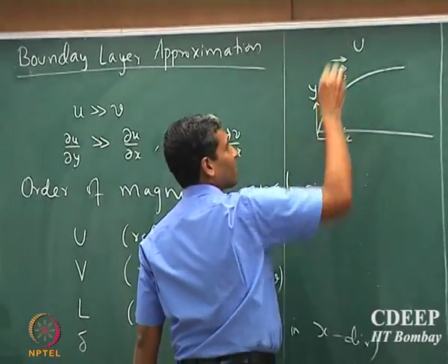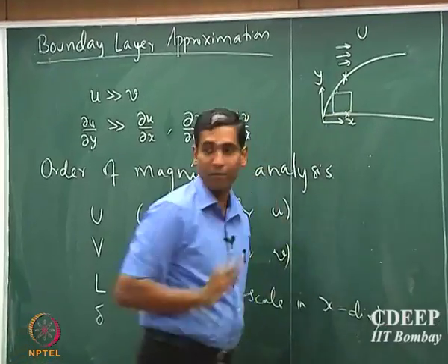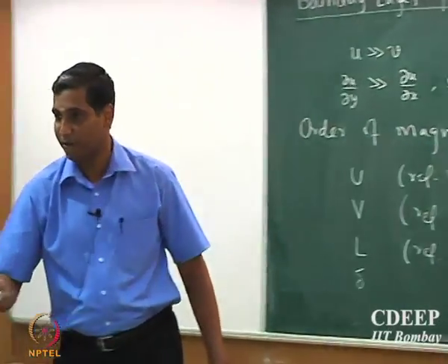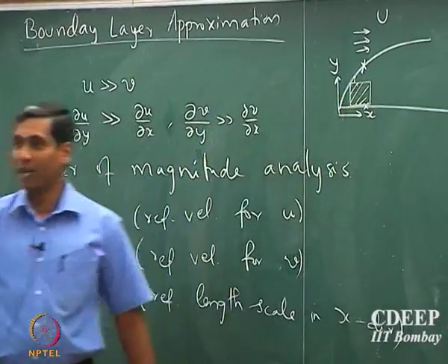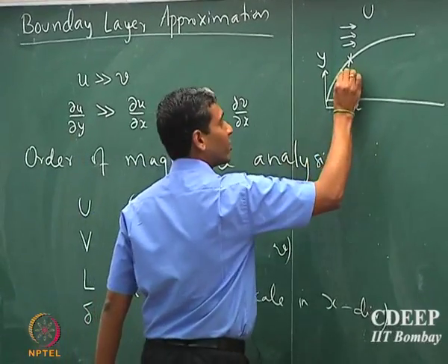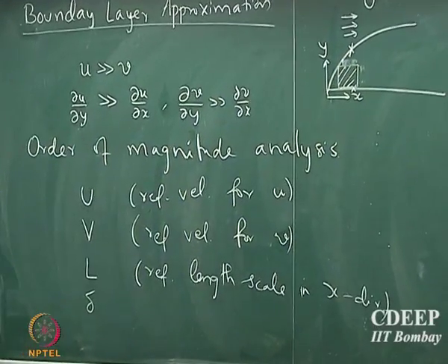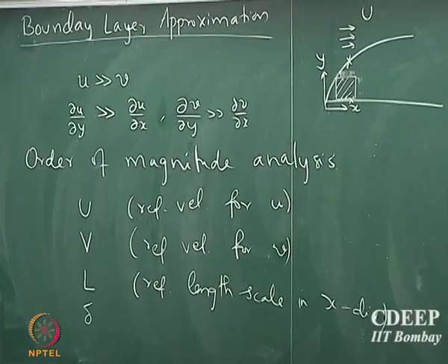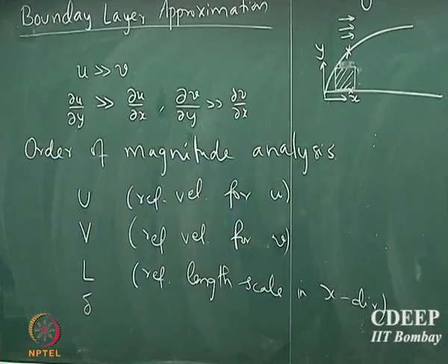No, you will not, because if you write a continuity equation, suppose this is your control volume. Here you are definitely going to see fluid moving out of the control volume, because this is inside the boundary layer and the fluid stream is still experiencing the friction offered by the interface.